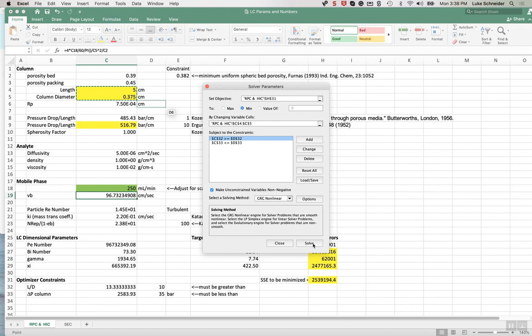Sometimes it's not possible to use the same packing, and you may have to play with that. You pick packing with the same surface chemistry, but it could be a larger diameter, it could be a smaller diameter. Typically it's a larger diameter. It may have different porosity factors, it may pack differently. You have to get all that information from the supplier.